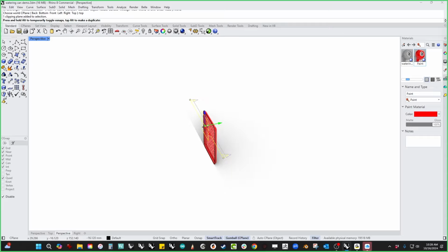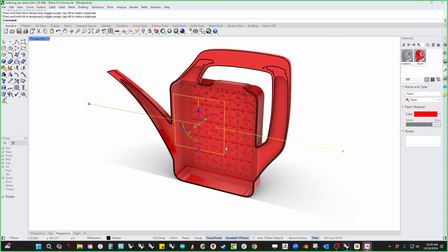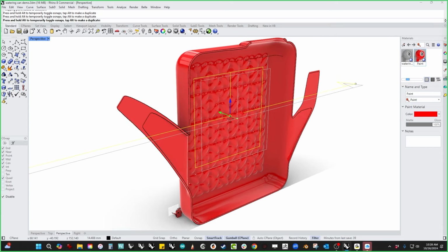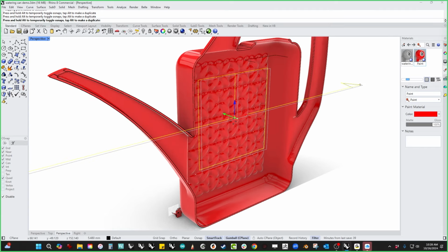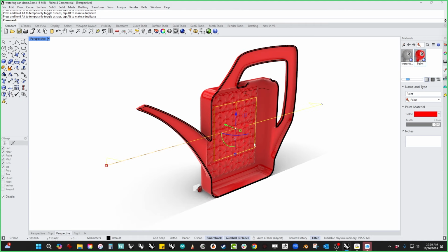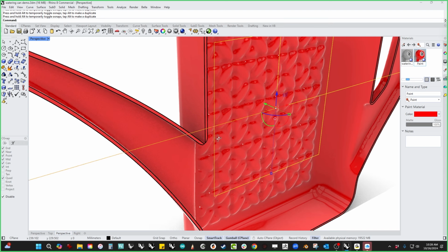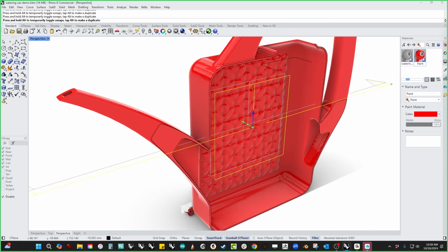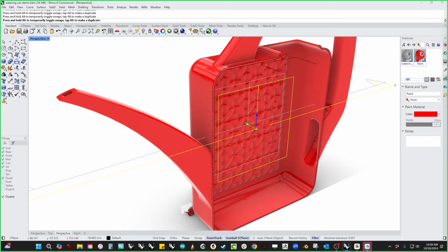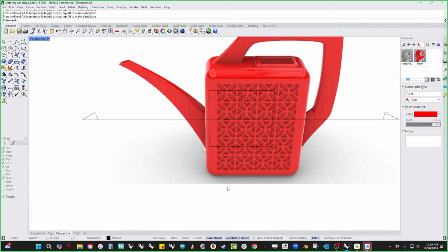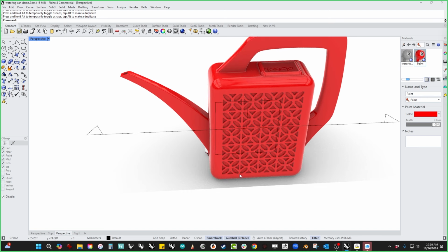As we drag through this thing, it's nice and shelled. Okay, nice consistent wall thickness. Voxels doesn't bow tie. That's the one nice thing. So down here, you can see that it's created a nice wall thickness in that area as well. And it's good to go. So this is something that could print and would come out just fine.